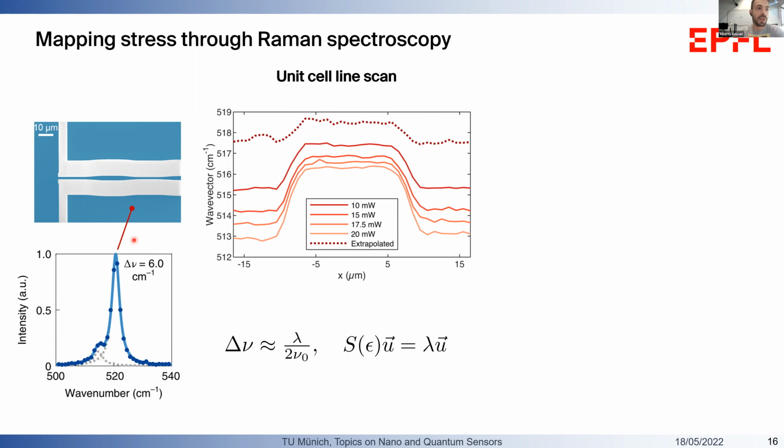It's very weak compared to the main peak, because the strained silicon is just around 12 nanometers thick. The interesting part is that the redshift between the main Stokes line and this satellite peak is proportional to the strain, in a way that can be found by solving this secular equation that relates the local strain tensor with the compliance or stiffness coefficients of atomic bonds.